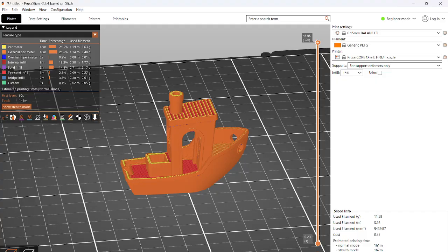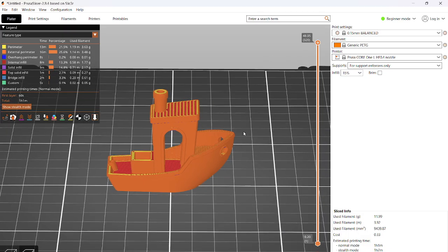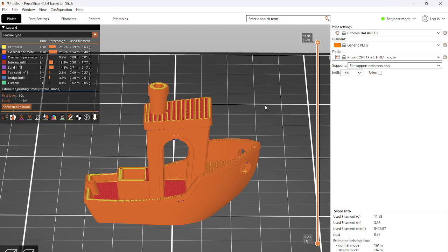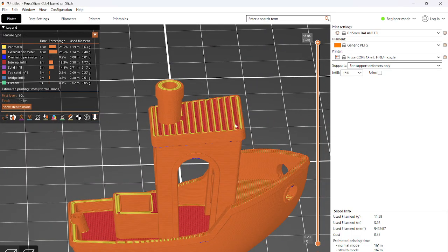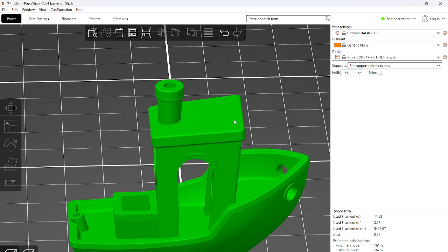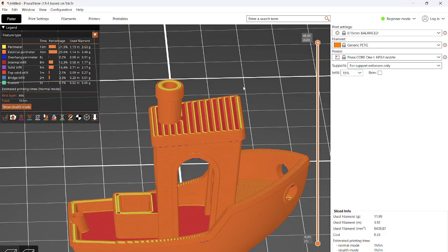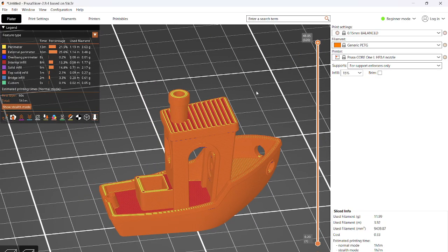So I'm going to switch back and forth between the editor view and the slicer preview. This is currently the slicer preview, and this is what your model should look like when it comes off the build plate. You can see there's this stair-stepping effect on this top surface, right? It's because it's a very shallow angle. If you look at the 3D model, it's nice and smooth, right? But because the 3D printer slices planarly, it'll stair-step when it hits stuff like this. So it's technically an approximation, but it's usually pretty good for most applications.